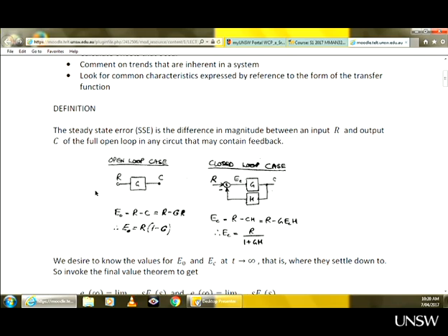Okay, so this is an open loop error. It is open to any deviations in terms of the parameters of what we think is constant in the transfer function, and also open to influences of all disturbances that may affect our system. In a closed loop system, the closed loop error is here, as we just agreed a few minutes ago. So closed loop error equals R minus this signal here, which is CH, R minus CH.